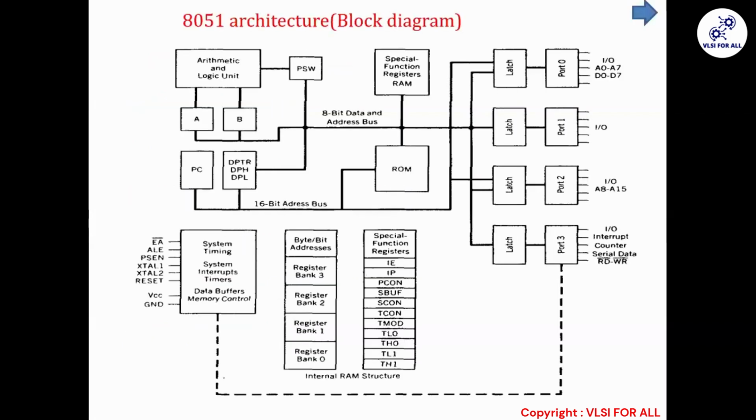This might seem difficult to you. Let me check the messages. Is the instruction memory address 16 bits, so DPTR is also required to be 16 bit. It is the data pointer. Talking about the data pointer in detail at this instant is not possible. That's why I have not told you. I'll tell you what it is. Okay, 2 to the power 12 is right, it is giving you 4096. We'll talk about the data pointer. Don't worry.